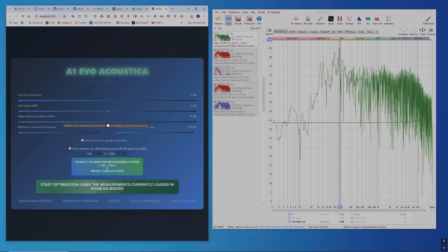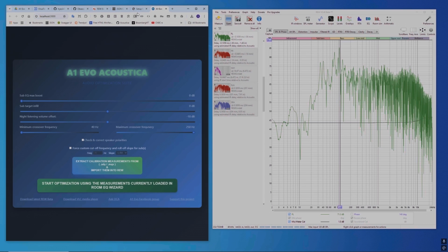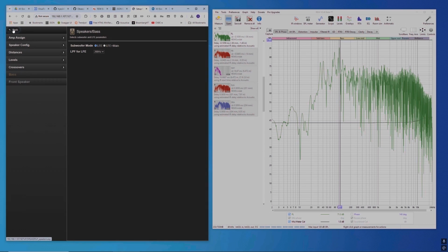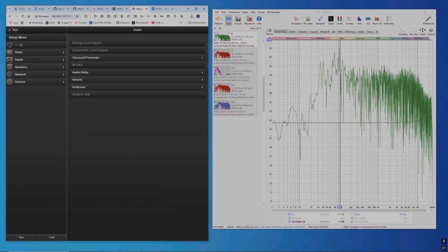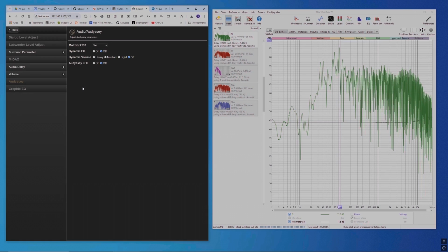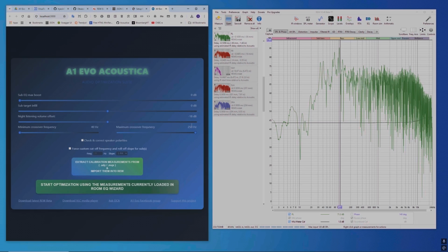And when you switch your amplifier to Audyssey reference, that will be for your low volume listening. You will suddenly hear an increase in bass and high frequencies. So don't use this mode with regular volumes unless you're a real bass freak. Flat is where you want to listen, and reference is only for night listening at low volumes. At low volumes like minus 25 dB lower volumes, okay?